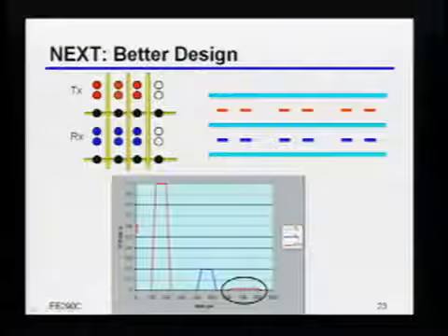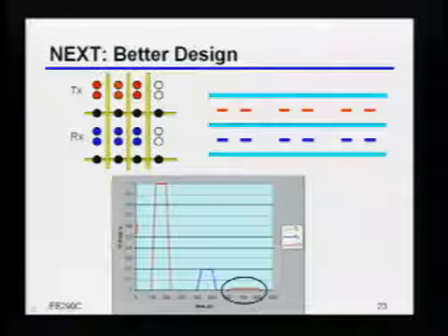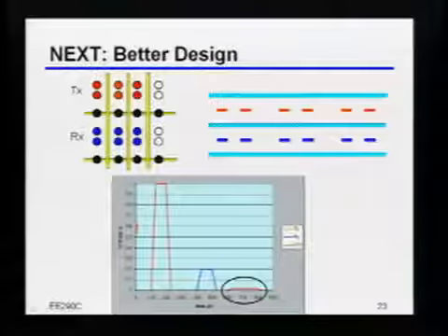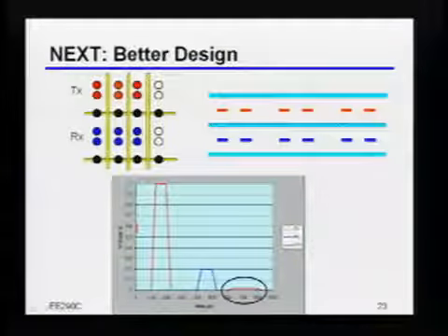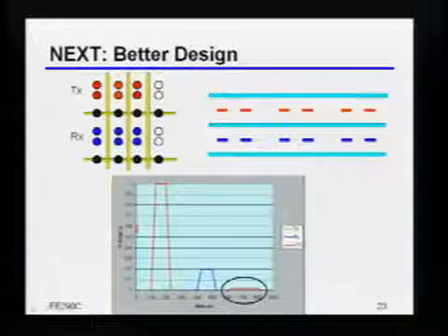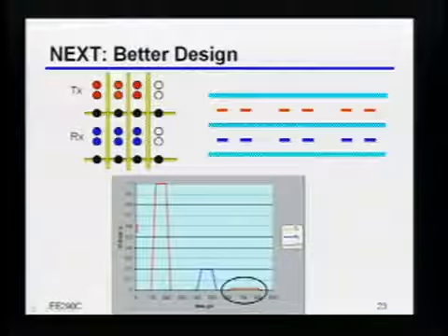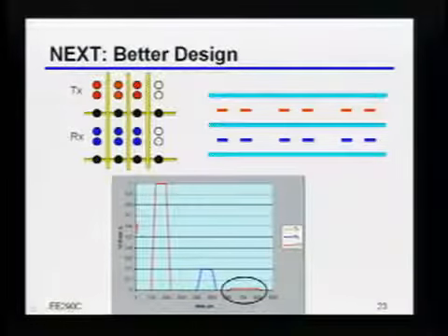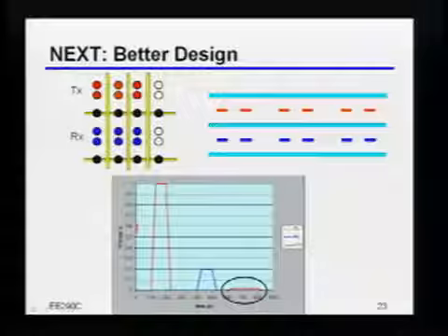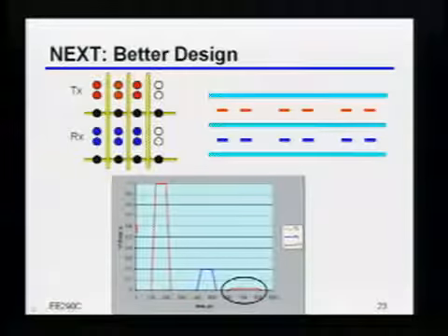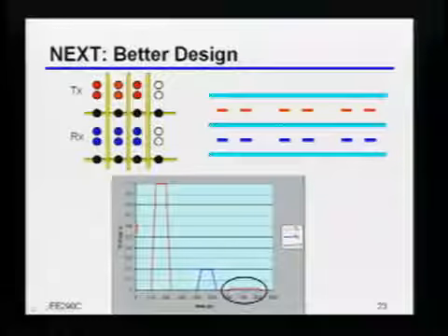The practical issue you tend to run into is, if I'm going to build this transceiver, I probably want to sell it to a bunch of different people in a bunch of different backplanes. So I might not necessarily know that this particular receiver is the thing hit by this particular transmitter. In fact, if you think about one of these really big chips, and these really big backplanes, and you look at the link budgeting that people will do, you may have 5 or 10 different crosstalk sources from 5 or 10 completely different switch chips, because in that backplane, all those signals are running next to each other. In the connectors, they may be next to each other. I may have some vias somewhere that are causing some of those reflections.